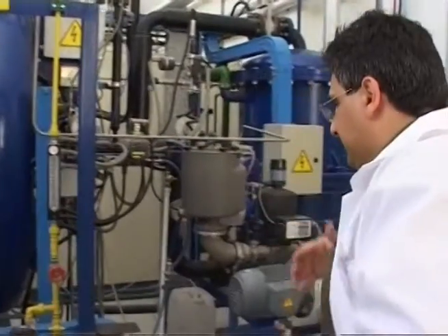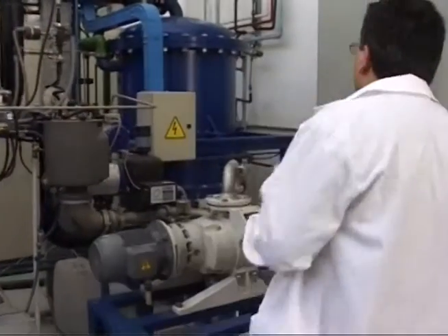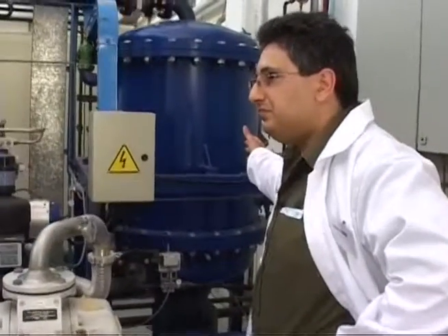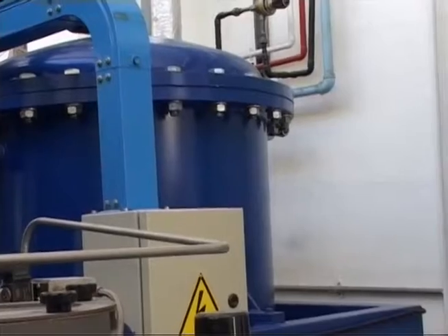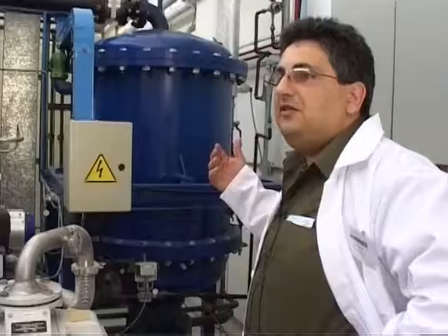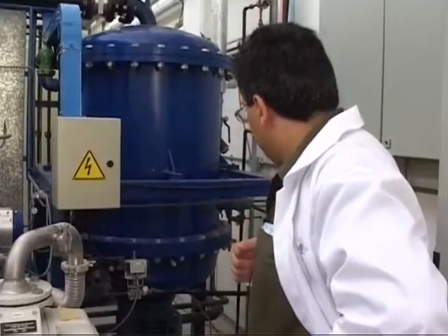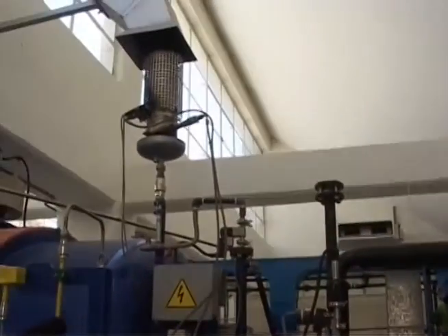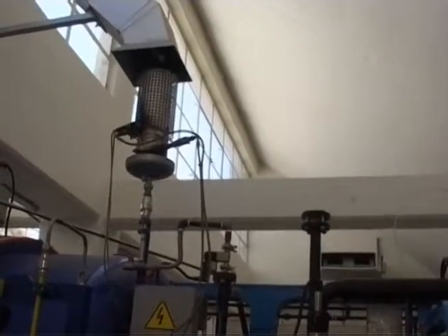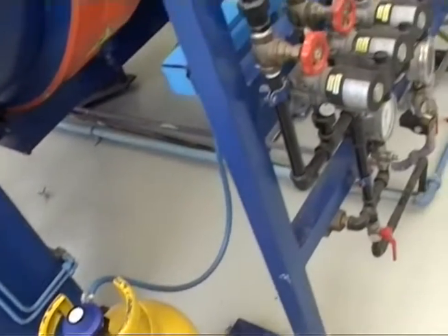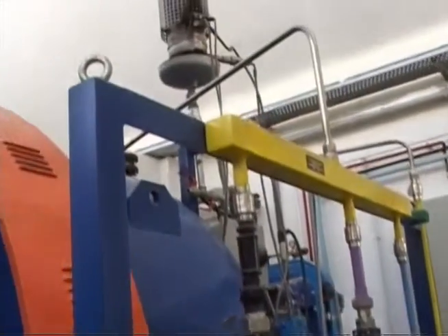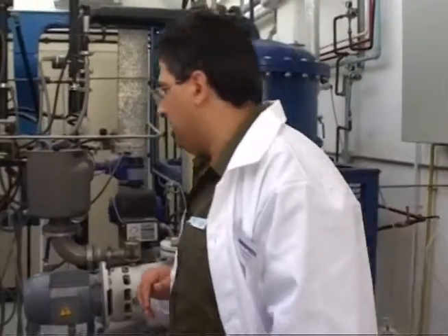coatings or surface modifications. At the back of the furnace, there is the heat exchanger, which cools the nitrogen during the cooling process. While at the top, there's the burner, which burns out the hydrogen and ammonia residues, which are exhausted into the atmosphere. So they are rendered harmless before entering the atmosphere.